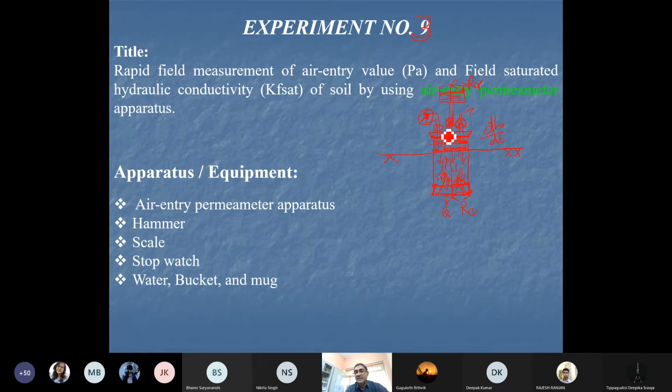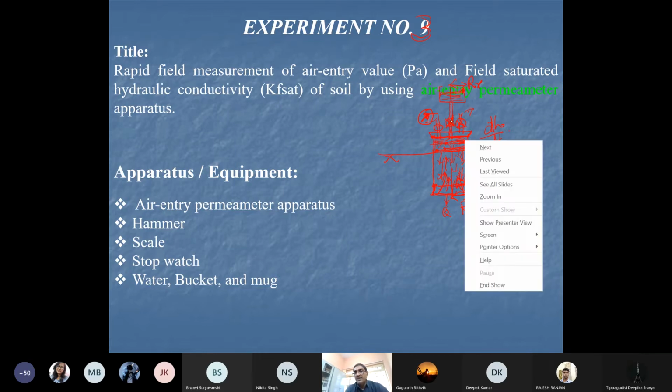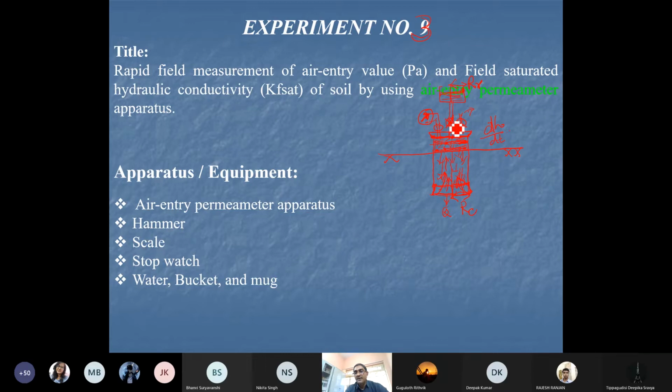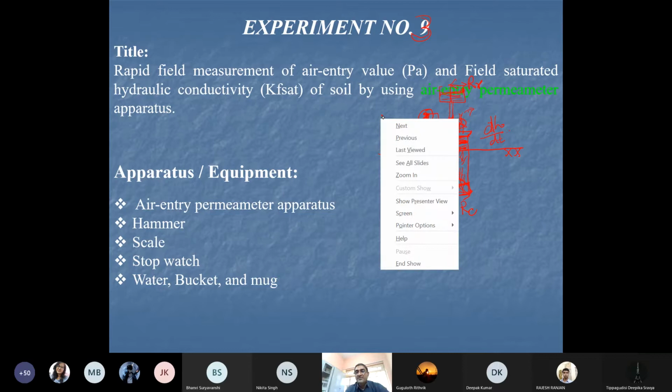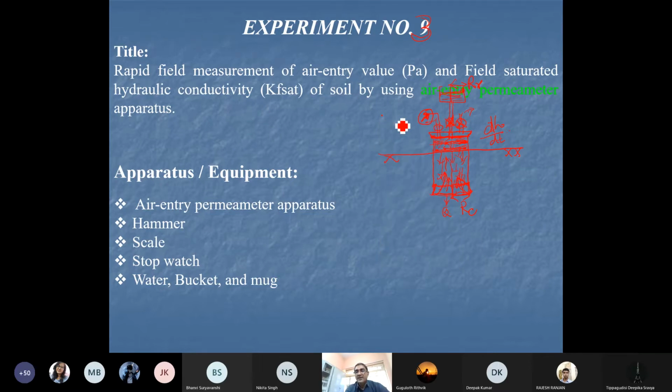So what will happen to the suction? Initially there was no suction, when we closed this tap of supply water. After a few seconds or maybe a few minutes, there is a suction, meaning a drop in pressure. So suction will increase the moment water is entering the soil, and trapped air is moving up to fill this created vacuum.